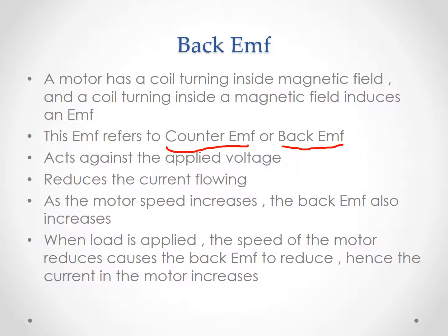Back EMF occurs when a motor acts as a generator, and it acts against the applied voltage, which means it reduces the current flowing. The applied voltage will cause current flow. That means the wire will experience a force, which means it starts to rotate. Therefore, the wire will experience a change in flux, and a change in flux will produce an opposing EMF, or a back EMF.